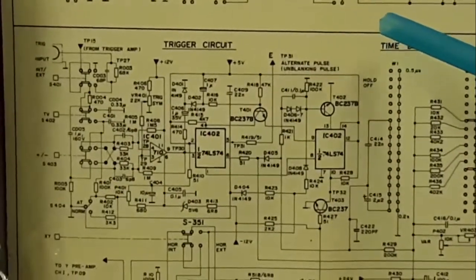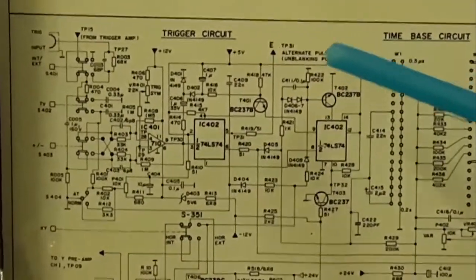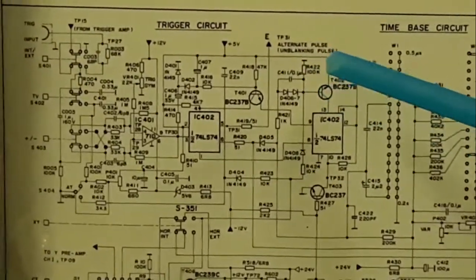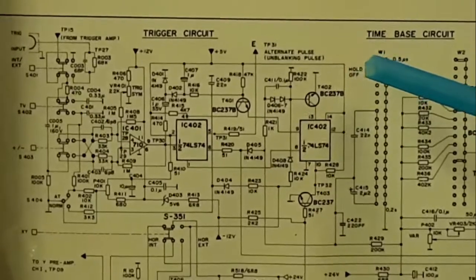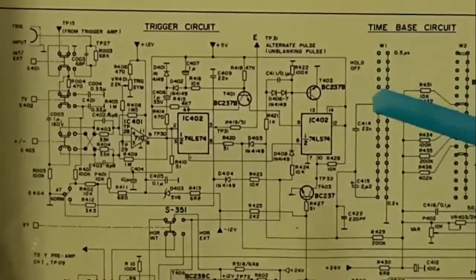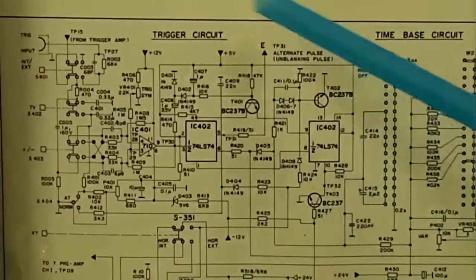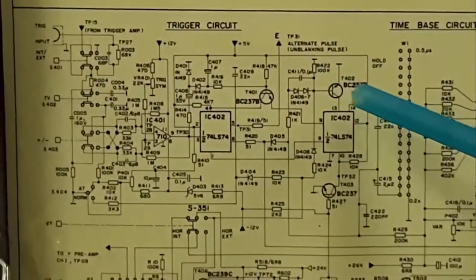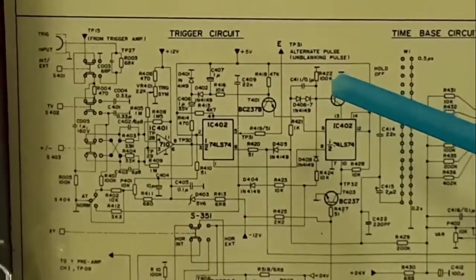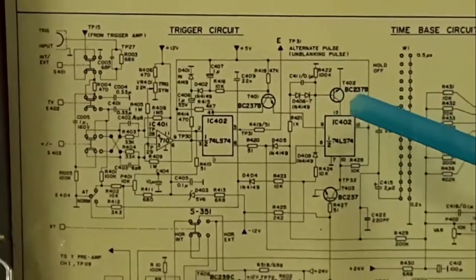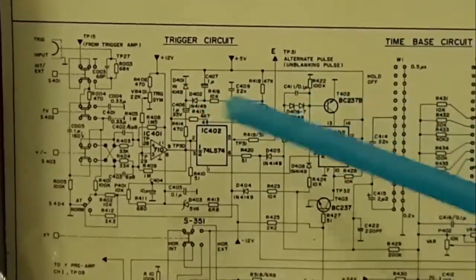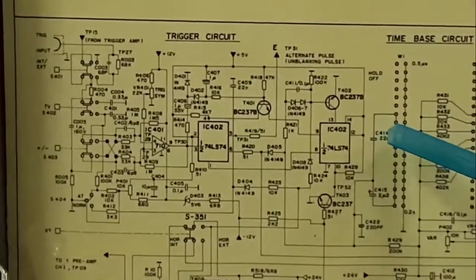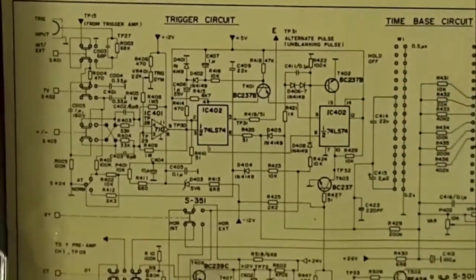But what does the conversion mean now? If you have a square wave, because the CRO is working on the AC signal, this square wave is of very big duration and a very big amount. So that's why multiple RC sections may be available in the trigger circuitry, so the square wave can be converted into a spike. Because the spike has a short duration and high amplitude, it can trigger the circuitry and show the time-based signal, or the sawtooth wave signal, or the sweep signal that is responsible for the synchronization at the CRT screen.